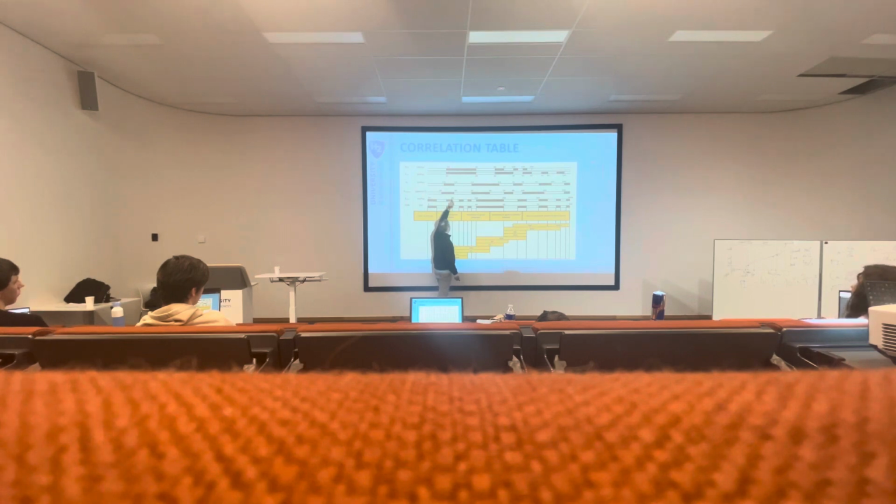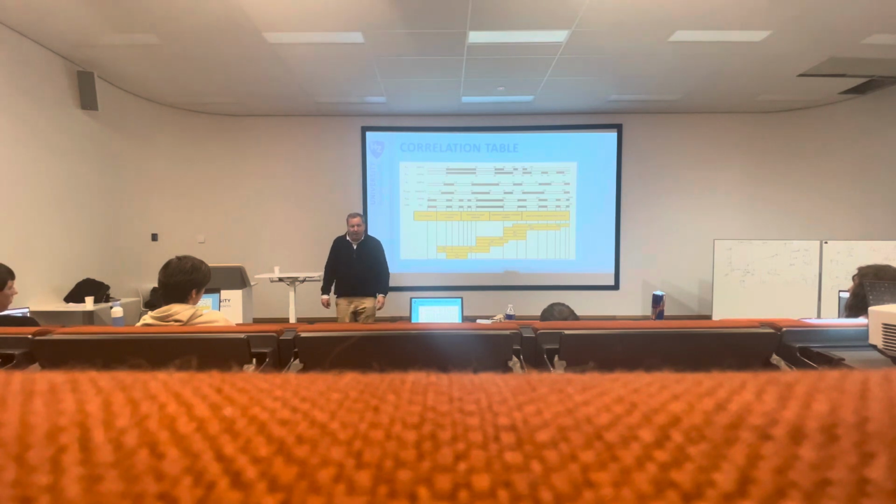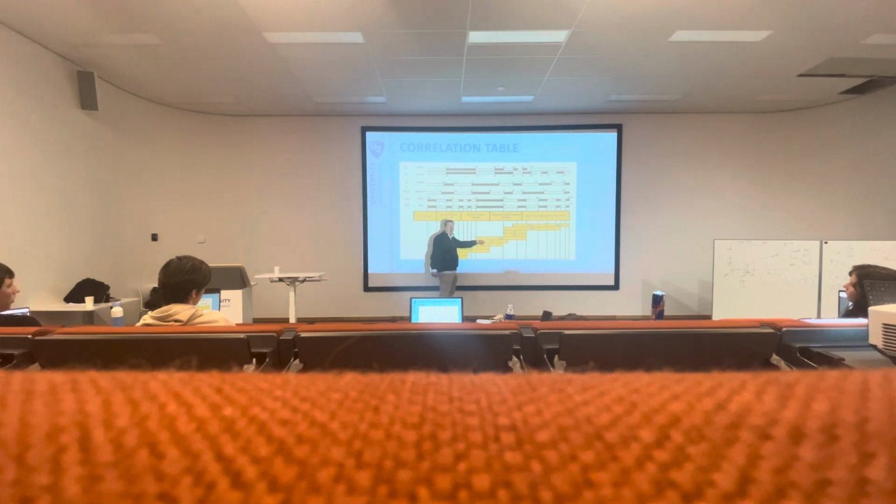Your K factor, which is used for concrete and more rigid pavements to see what the strength of the soil is, you know it's about 35 or 38. The QC value, EV1, EV2, and plate tests, and you can also see what type of soil it could be. So when somebody says we have a CBR value of 5%, then you know it can't be sand, because sand has a higher CBR value than 5. That's why it can be useful to quickly compare.